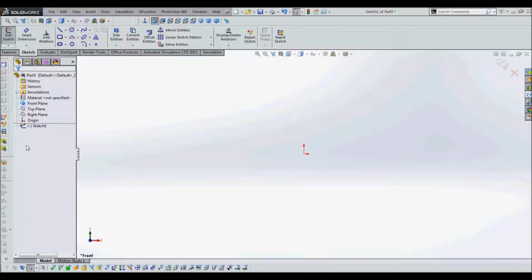As we continue to work on the part, you'll notice that every feature we make, every sketch we produce, and every extrusion or cut that we make will show up here as a feature in the feature tree. And this is what allows us to go back and make modular SolidWorks designs. So if we were to design a part and we determine later on that we need to change its critical dimensions, we can change something earlier on in the chain, and then everything will propagate downward through the tree and update our final part. So if that's not clear right now, that's alright. We'll be going over it a little more later. But for the moment, let's start out drawing our first part.